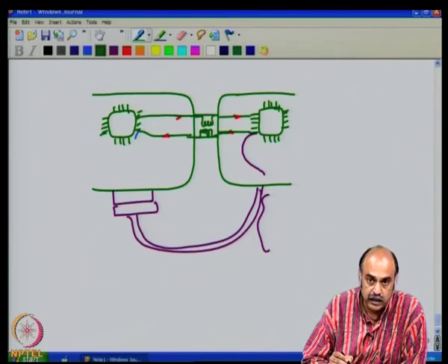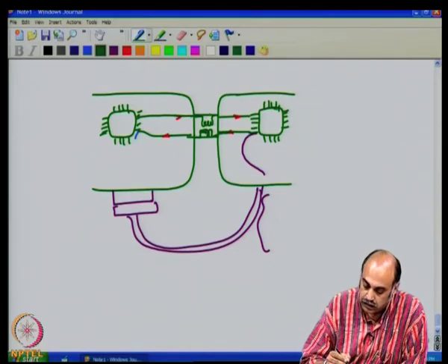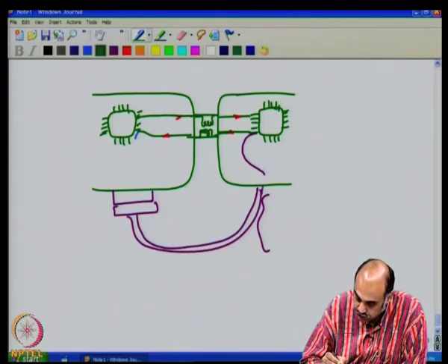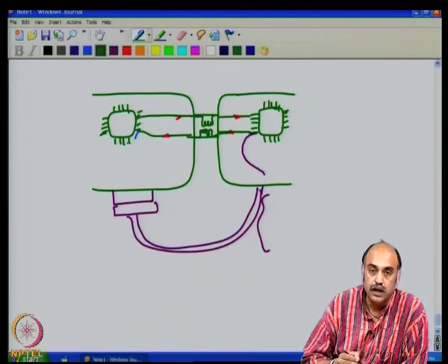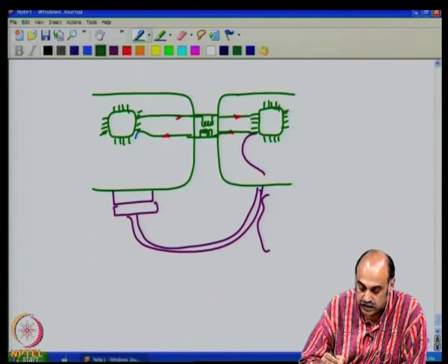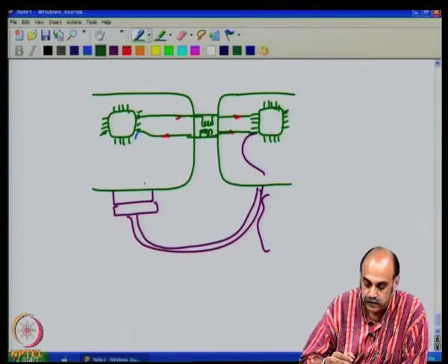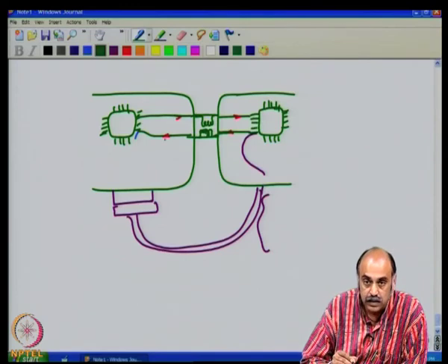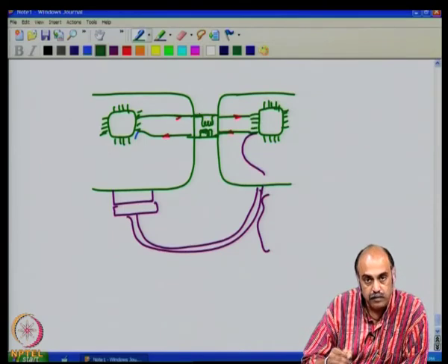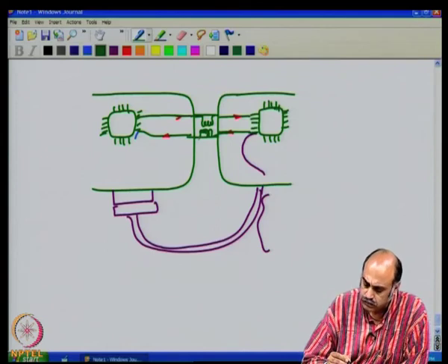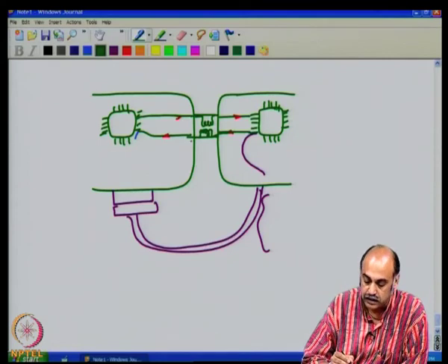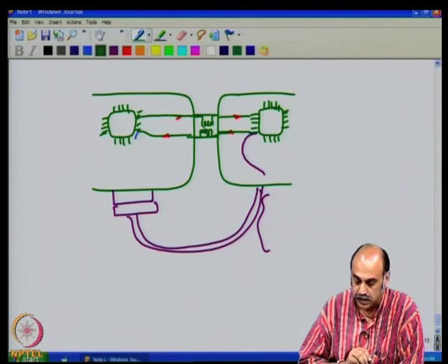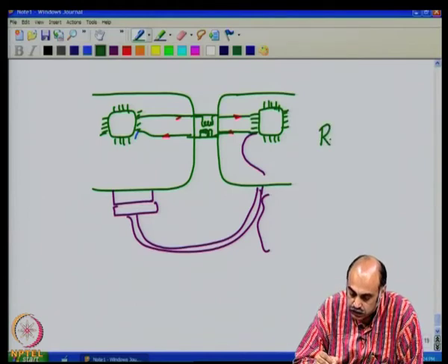This inductance does not act as an impedance, but it forms an impedance for the current which does not return through this, but returns through another path. So, therefore, the impedance of all other external paths will increase and the impedance for the local path is reduced by putting this common mode choke, and thereby you try to retain most of the return path current here and reduce the loop area. So, the idea is reduce loop areas.